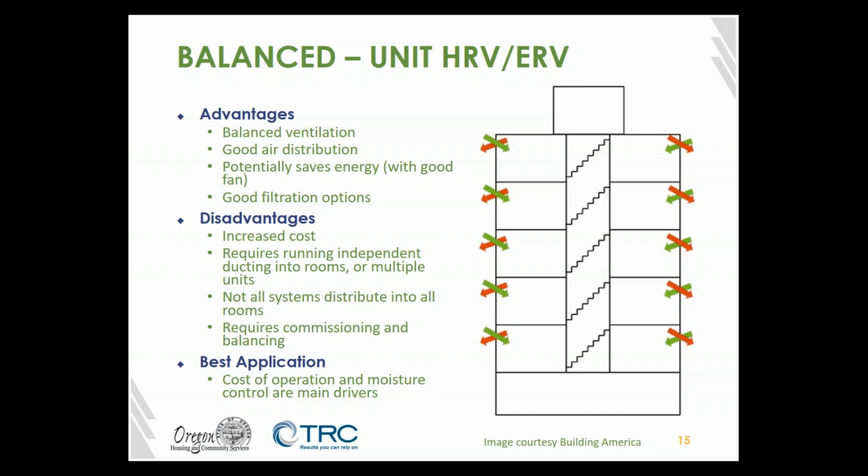That being said, there is an increased first cost, which we'll get into in a little bit. It does require running some independent ducting. It requires commissioning and some balancing and some thoughtful engineering. With exhaust and supply, there's a little bit of a slap it on the wall, it'll take care of it. With balanced, you have to plan, you have to think it through, you have to follow some good engineering best practices. And that takes thought and experience and a little bit of increased upfront cost.